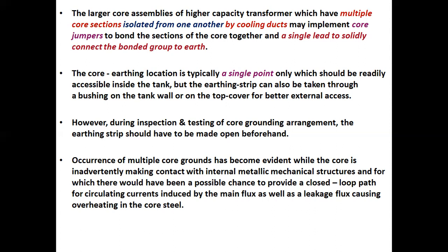However, during inspection and testing of core grounding arrangement, the earthing strip should be opened beforehand.